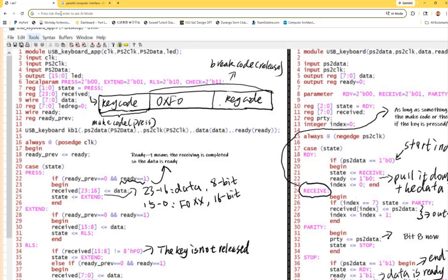So it's outputting one letter or multiple letters, right? The way they do it is to plug in the 0xF0 in between the key code. Keep in mind, it's not always just one key code. Whenever you press it, there will be thousands of key codes being created. But when we release it, there's just one 0xF0 being plugged in the middle to show that this is one release.